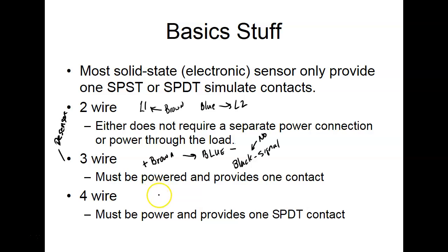Okay, correct. A 4-wire sensor, what's going to point toward plus? Brown. What's going to connect to the minus? Blue.